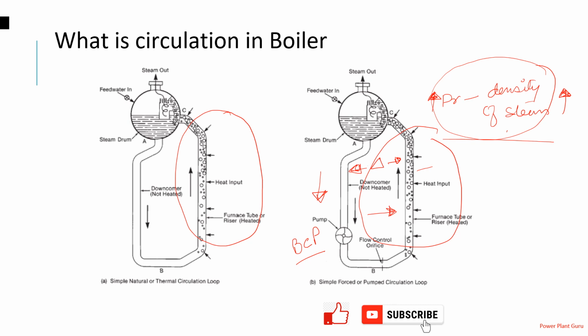And similarly, if you see the once-through boiler, the supercritical boiler, at this point the water and steam density will be equal, so that water is directly converted into steam. There is no intermediate phase. So there, this circulation is not required. That is why it is called a once-through boiler.